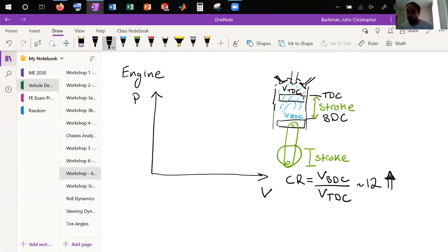Knock is basically a flame that starts because of the high pressures and temperatures, not associated with the spark propagation of the flame from the spark. So it's not always that when the piston travels up that it pre-detonates, but even just after the spark is going, around the outsides, away from your spark, you'll have little detonations that begin to happen. And usually there are acoustic sensors in your engines these days to help prevent knock, and if they sense it, they'll put in some control from their ECU to help avoid it, probably power your engine down for the most part, and figure out what's actually wrong with it.